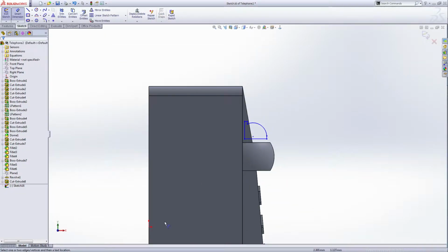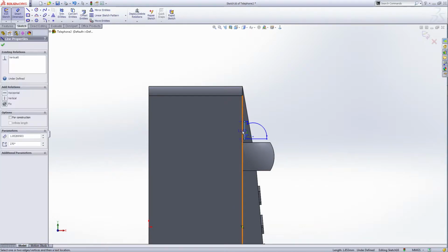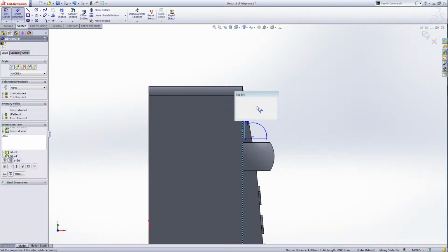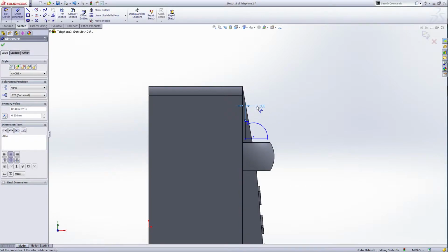Okay. We can use the center up here, or you can draw a shape and fully define this sketch. I'm gonna use the sketch I did before. So I've already defined this and got the distance. So first is this edge to this edge. Distance is 0.3. A little bit apart from each other, not connected.